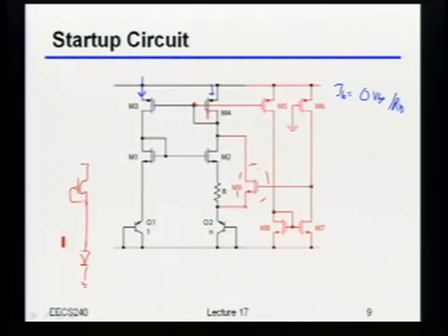The other one is a positive feedback with gain. There we go. Right, so remember the whole trick here is I've actually got both positive feedback and negative feedback, right? Because if you follow the loop one way, you get positive feedback. If you follow the loop the other way, you get negative feedback. So the real trick here is that I wanted to make sure, by tying it this way, this was the only way to guarantee that the negative feedback is larger than the positive feedback.